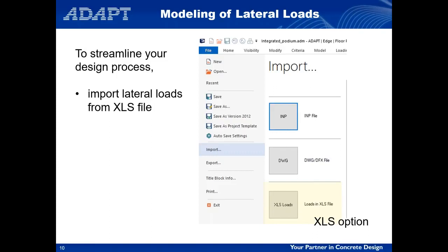That's just a quick way to get around knowing what the actual XY coordinates are of the specific load points, and then using Excel or INP makes it easier to enter those loads, so that you're not typing individual values in Builder, as opposed to Excel, which is more efficient for that.